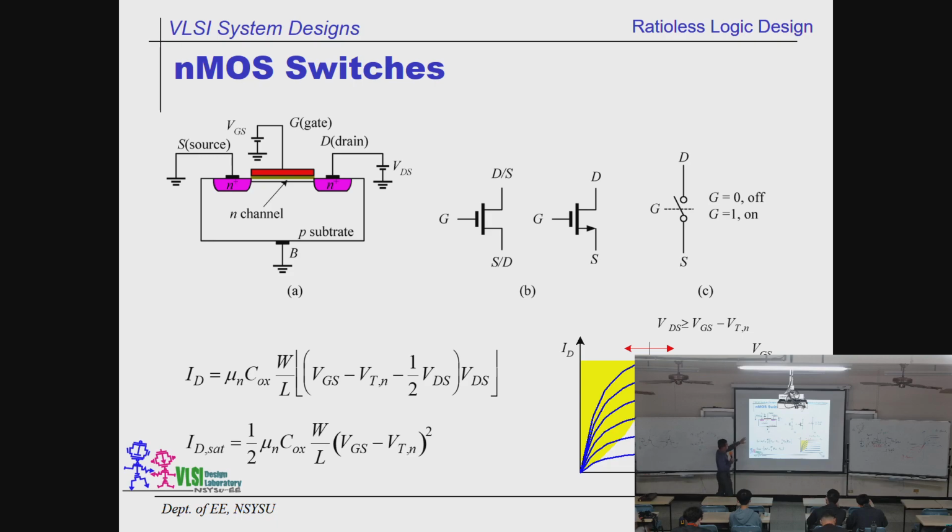This is a schematic. This is the side view of a P-channel device. You have a gate, a source, a drain, a channel, and it follows the square rule. This is the size, mobility, (VGS minus VTH) squared, and this is what you're supposed to get over here. And these are the symbols over here. If you don't draw the arrowhead, it could be a source or drain, either way. But if you do draw the arrowhead here, the arrowhead goes to the source. That shows where the low voltage is.